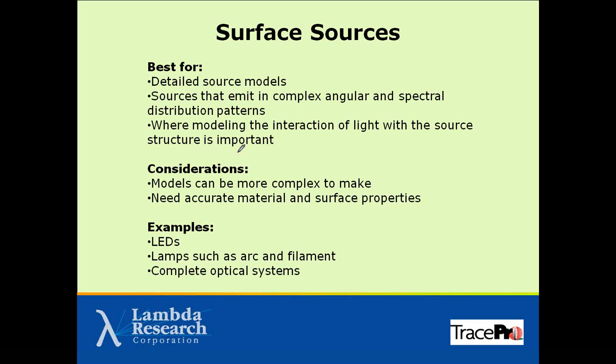Now we're going to look at surface sources. Surface source is probably the most versatile source in TracePro. Good choice for a detailed source model where you're modeling all the structure, the packaging, glass, plastic, the surface and material properties. Good choice also if you have a source that emits with a complex angular and spectral distribution pattern.